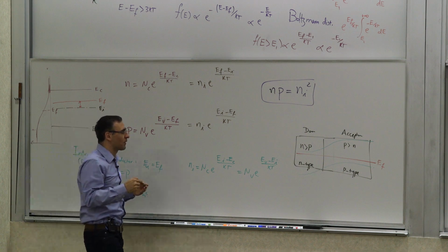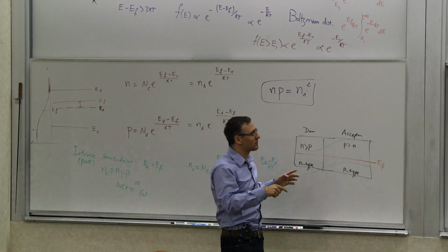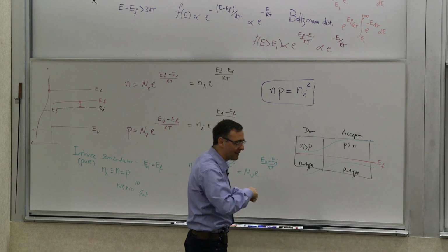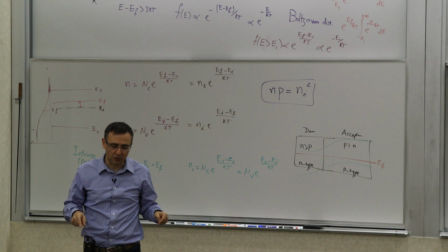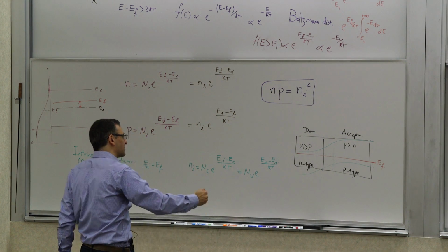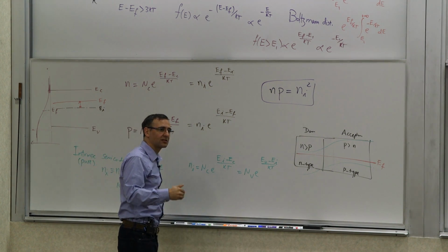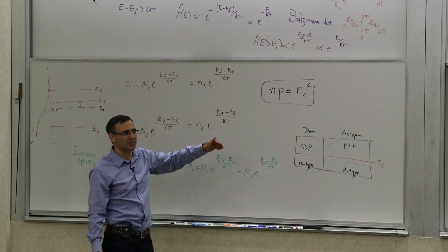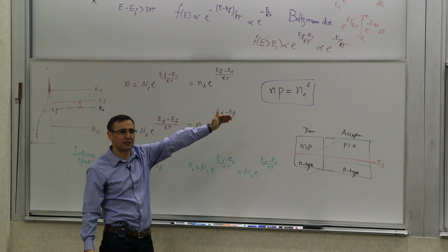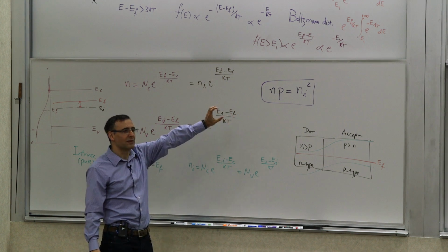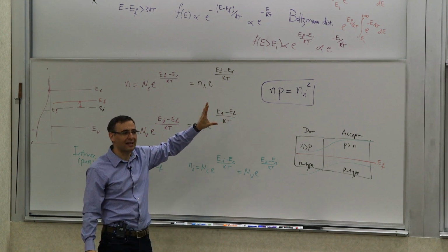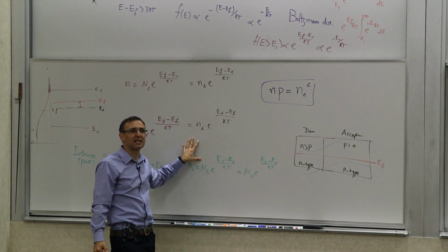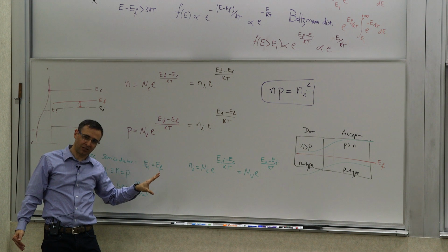So next time, we'll take this and use the energy distribution, as well as the velocity of movement of electrons inside the semiconductor, to find the conductivity and resistivity, which we started with today. Now we are going to calculate the conductivity in terms of these microscopic parameters. And we'll see what makes a semiconductor really a semiconductor.